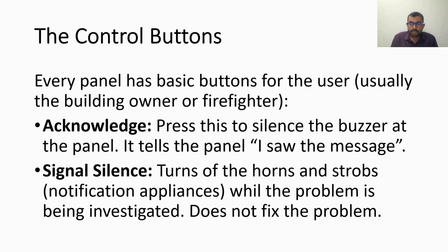Now comes the signal silence. The silence button actually silences the horns and the strobes. Whatever notification appliances are there, it will silence them while the problem is being investigated. It does not fix the problem, and that is very important. Silence basically means to silence the notification appliances.